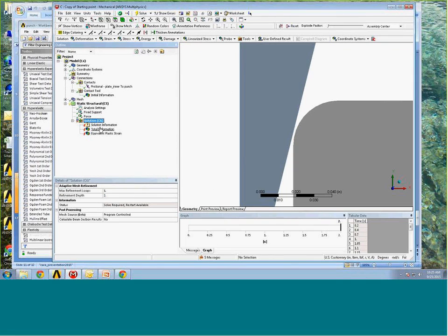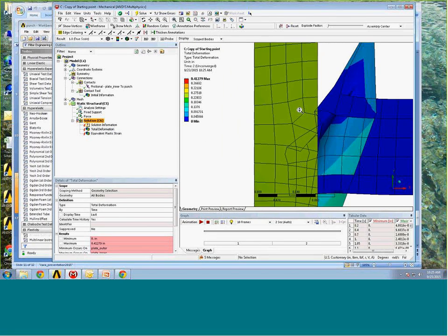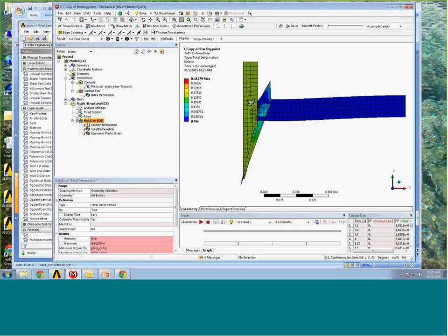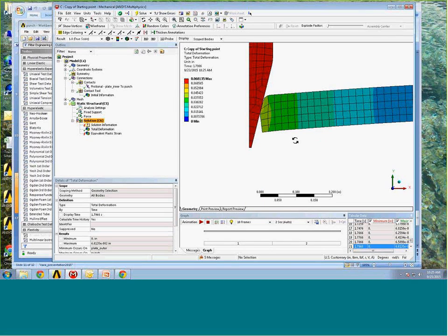All right. I can look at the results, and this is for the unconverged solution. That looks horrible, right? Severely, severely distorted element. I could look at the element solution prior to that. So I could pick that last converged point, retrieve that result. That actually looks fine.